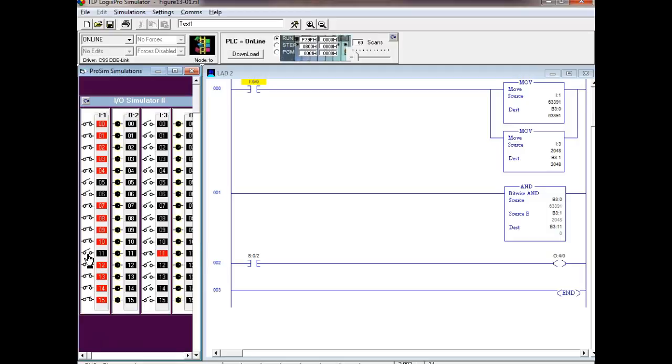Yeah. So we do these masks all the time, just to strip off things, and we get in all this information from thumb wheel switches. Thumb wheel switches are going to give you back all this information at one time, right? You understand? But you're trying to see if this one bit is changed, right? You understand? Inputting in groups and outputting in groups becomes very important. Instead of dealing with one bit at a time, what can we do with these instructions? We can deal with 16 bits at a time, or even 32.